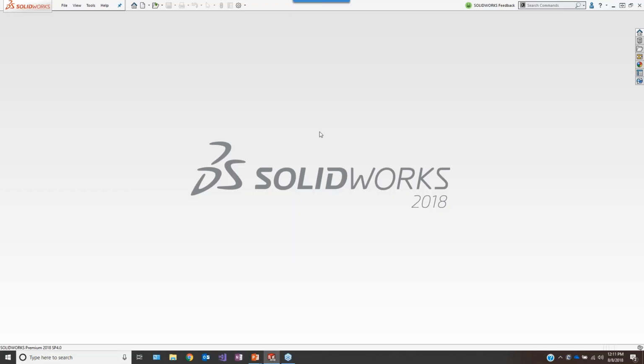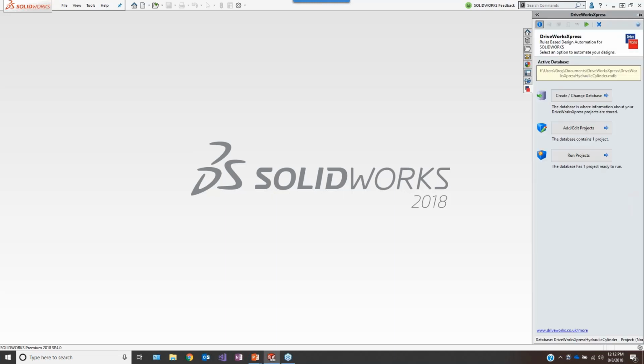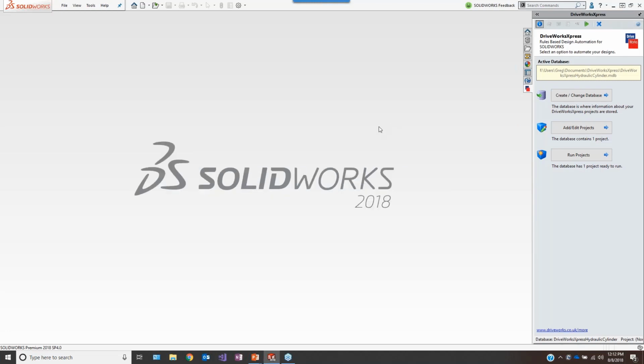But if I jump back into SolidWorks here, to turn it on, we're going to go to Tools, Express Products, DriveWorksXpress. DriveWorksXpress is really run the whole time through this window in the task pane on the right, and you can see that little blue square with the red square on top of it. That's my DriveWorksXpress window. I'm going to go ahead and pin that so it doesn't go away when I click off in space.